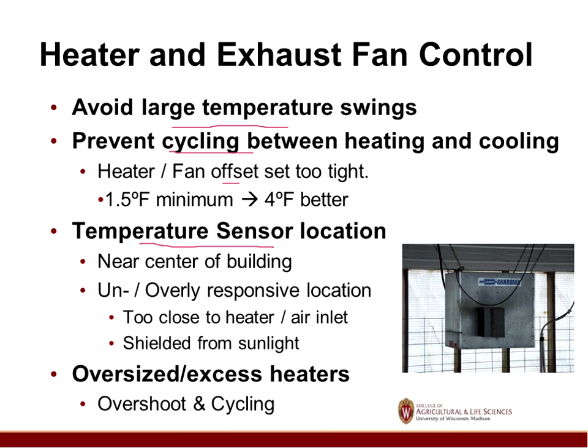We also want to make sure that the temperature sensor is sensing what the animals require and are sensing. Typically we want that near the center of the building, in an area close to the animals, but not so they can get to the sensor. One of the issues is sometimes I've seen them stuck in a corner or put in front of a heater or something, so they're over- or under-responsive. They're not sensing what the animals see.